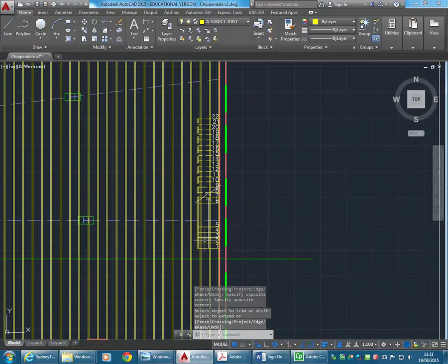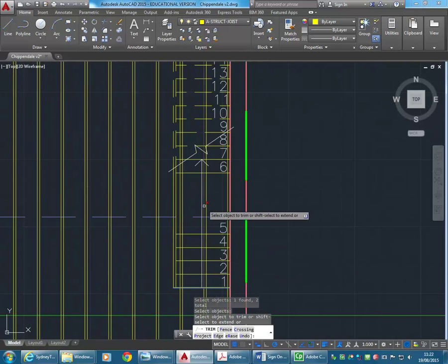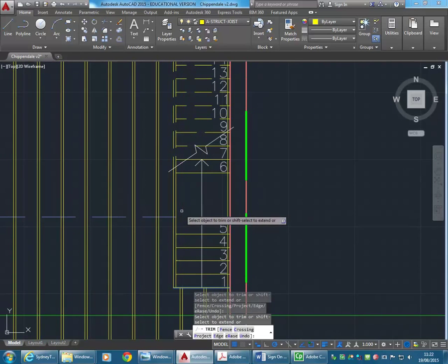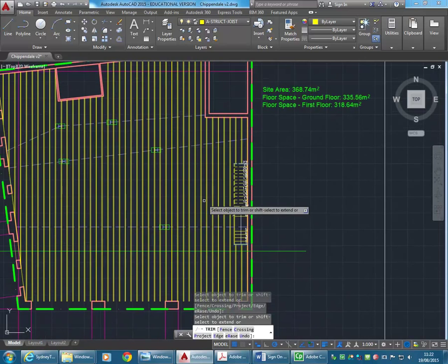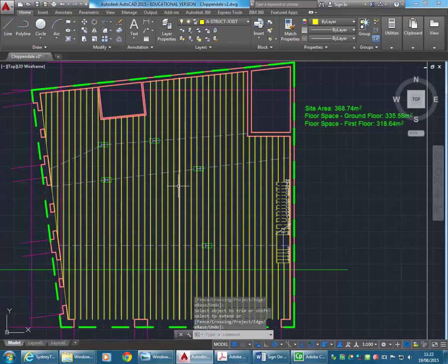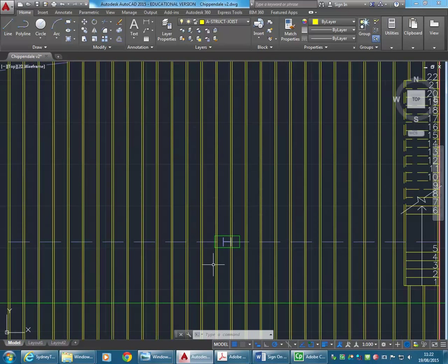Got to cut a hole for the stairs. So again, with trim, you can choose the top and the bottom step, should be enough. Pick the joists. That looks pretty good. And so then it'd be a good idea to go ahead and put in the beams. Since you're doing an interiors project and you're treating this as a finish, you want to draw it the way it looks, rather than having just a diagram showing the beam locations.